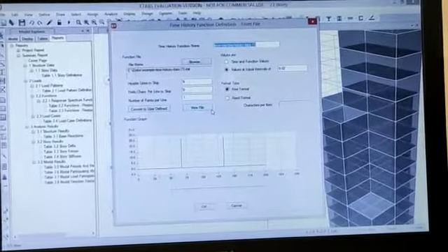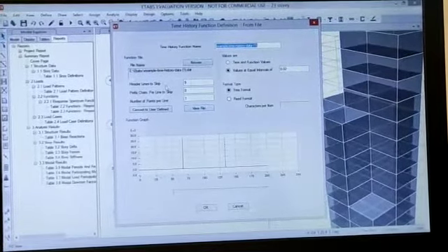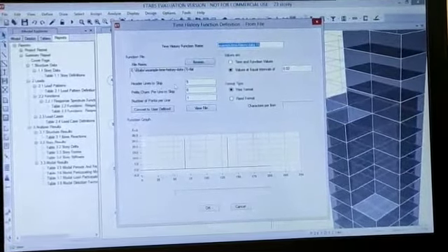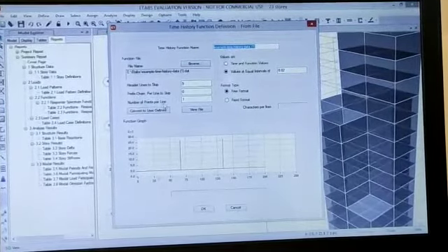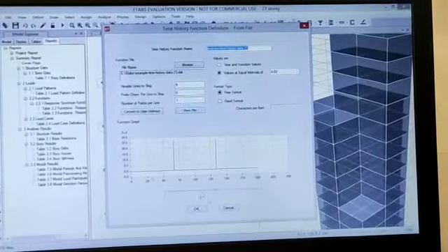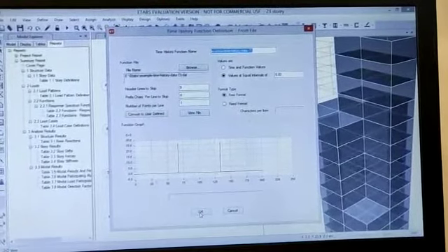For example, I have opened this file and select header lines to skip as 9, prefix as 0 and number of points per line as 1. Then click on OK.